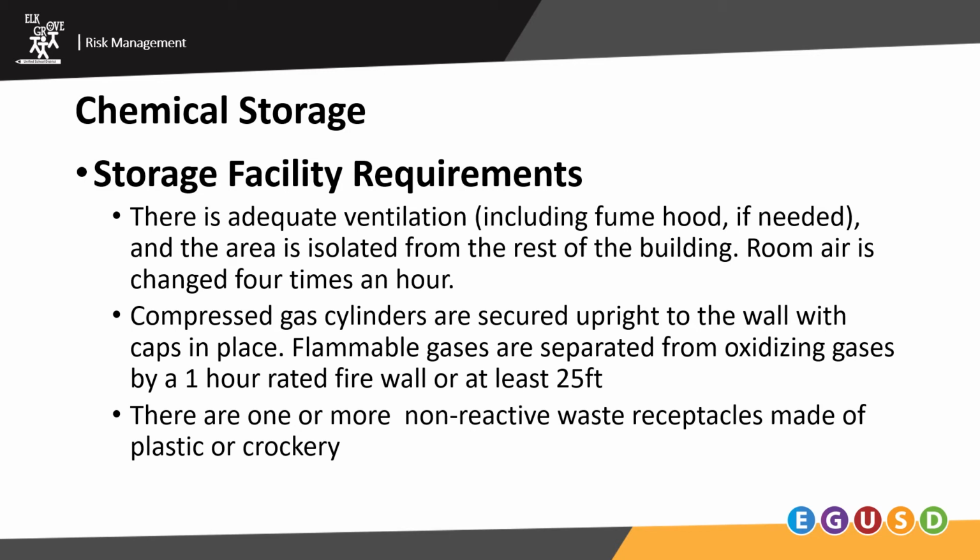Room air is changed 4 times an hour. Compressed gas cylinders are secured upright to the wall with caps in place. Flammable gases are separated from oxidizing gases by a 1-hour rated firewall or at least 25 feet. There are 1 or more non-reactive waste receptacles made of plastic or crockery.